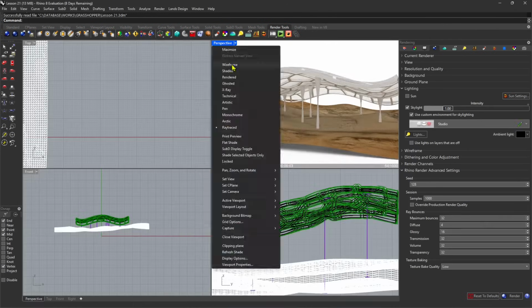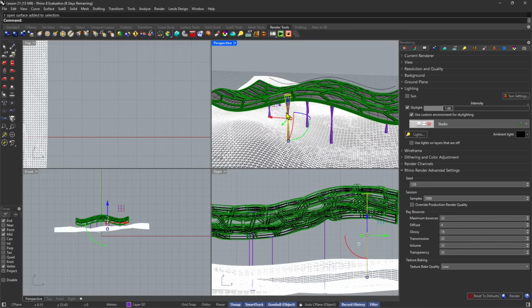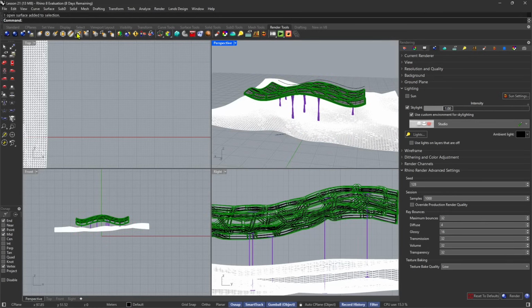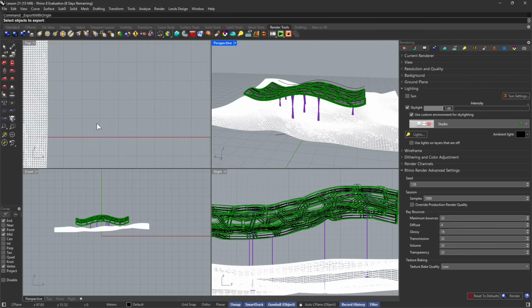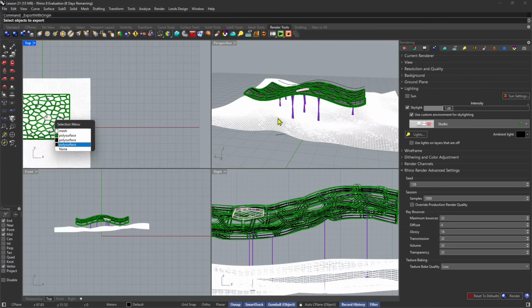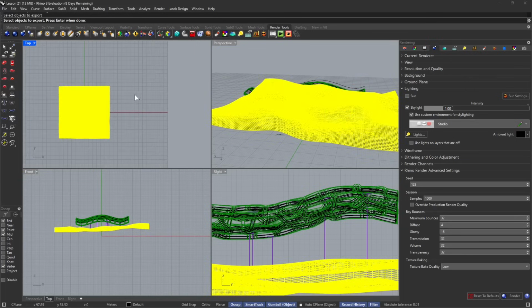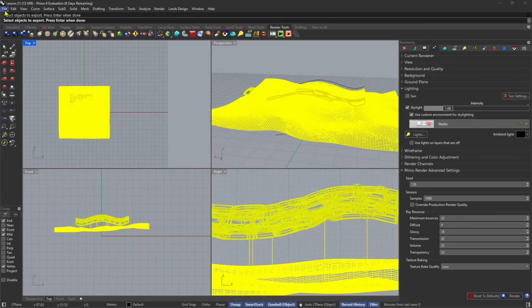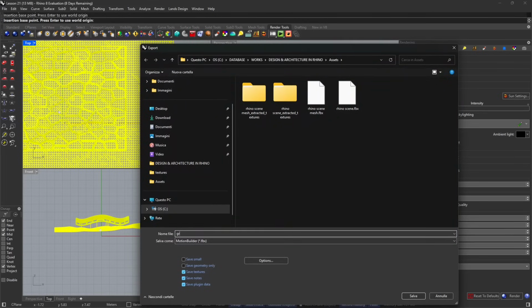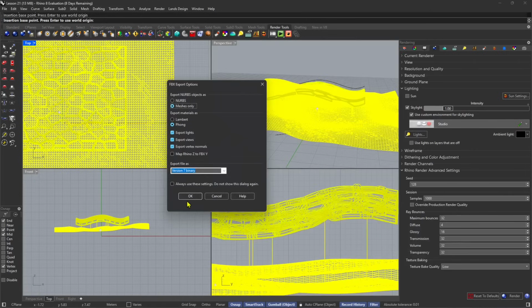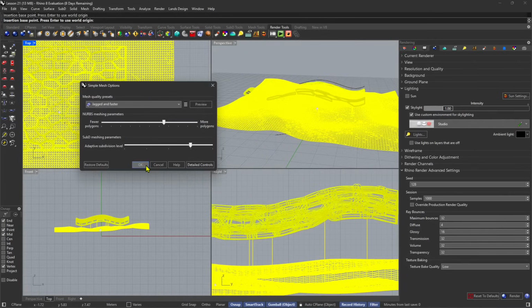Now to finish, this is a Grasshopper project, and also it will work fine. Remember, in Grasshopper you need to bake in order to have the final solid or the final mesh. Otherwise you won't be able to export anything. And again, I'm going to select the objects to export. I'm going to choose an origin, and I'm going to export. And you can use FBX as well, which is what I'm doing. So Grasshopper, scene, mesh. Also, if you use other formats, make sure you are exporting meshes and not NURBS.